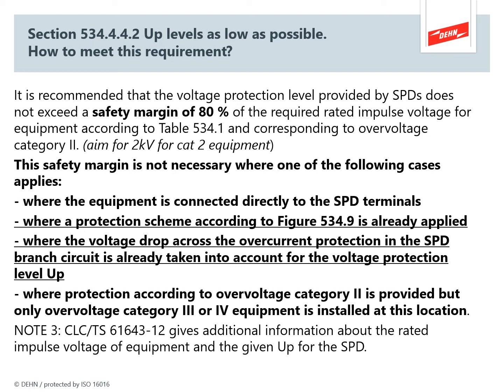And we also don't have to consider this safety margin where the volt drop across the overcurrent protection in the SPD circuit has already been taken into account. And this would apply to an SPD which has got a built-in fuse, and we're going to see what the advantage of that is for the panel builder in order to meet these requirements.